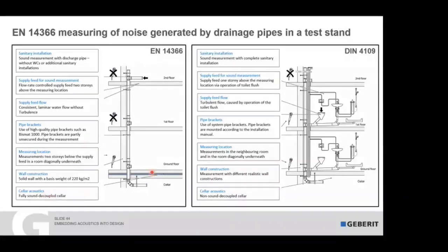Again, also the fully sound-decoupled cellar. Here you see the cellar is fully sound decoupled, and here we just use a realistic installation with the brackets, where the cellar is normally installed, and then also the noise which comes up from here is considered. So this is just to explain to you the reality, the facts, how this is done. This was not invented by any company. That's just reality. And most of the suppliers, of course, measure this here. And we, as we have our sound laboratory, of course measure the real situation, because afterwards on the building side, we also guarantee the values within the standards, which are between 30 or 35 dBA.